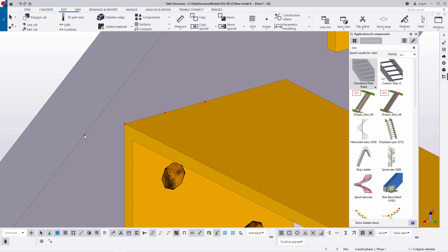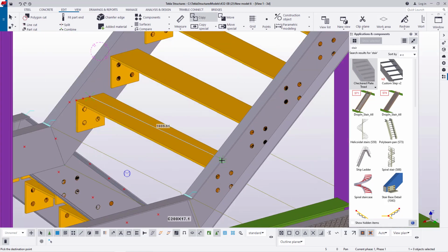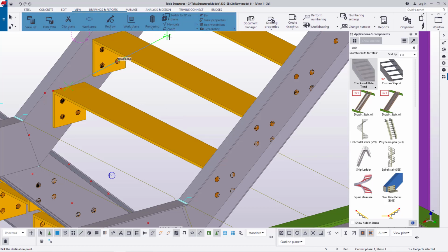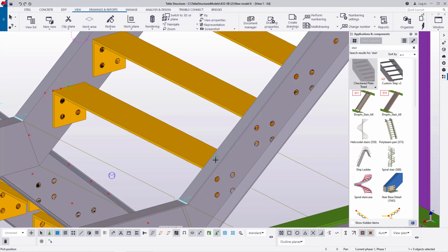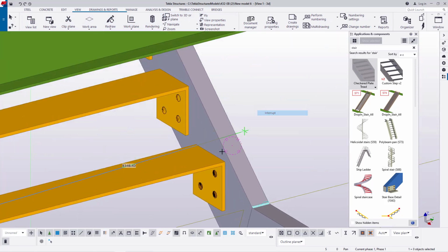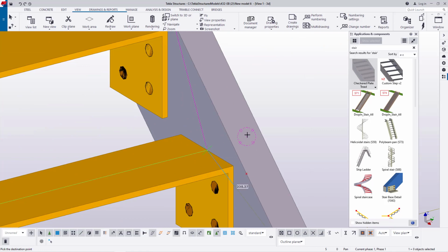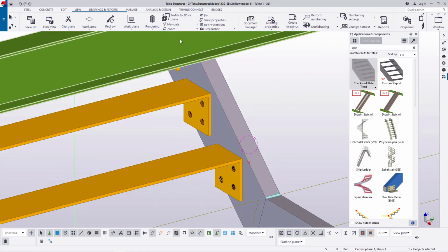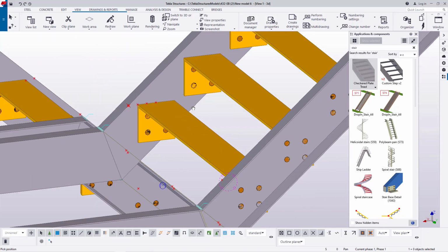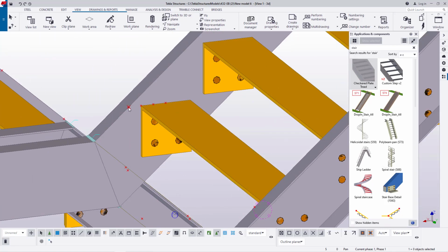So I'll select on this, right click and come to Copy, and I'll snap on the midpoint right there. So I want to access this end, but I cannot see the midpoint of this. So that is the reason why I come to View and come to Navigate and access Rotate with Mouse and left click and hold and turn this round and snap right there. So we have the 2 points in place, just to guide us all the way to the position that we intend to reach.